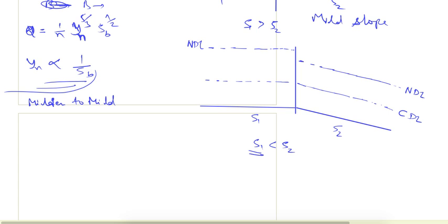So till here the flow will simply be carried on the normal depth line, and from here to here only the change in depth will occur, so this will meet the NDL like this. In this case we can see this is again a mild slope, and this is zone 2, so this will be the M2 profile.